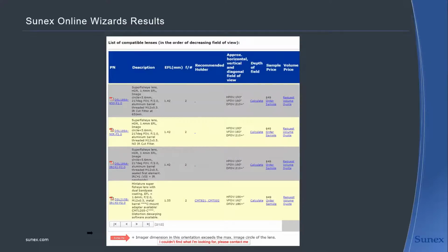Jumping in again here, we got a question on exactly this topic, and the question is: lens shading or vignetting, a function of the lens or the sensor? And this goes along with what you're saying here. I think if you interpret the intent of the question, it actually would be both. Lenses do have a phenomenon or feature called vignetting, but when you're matching a lens to a sensor, what you're actually seeing, if the image circle isn't large enough, is clipping of the image circle.